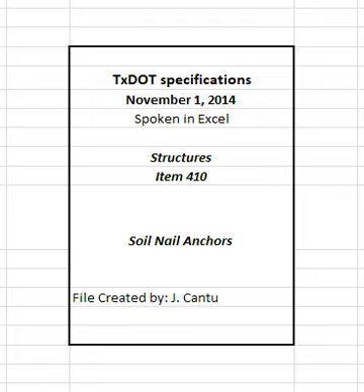Provide a neat cement or sand cement mixture for the grout for soil nail anchors with a 7-day compressive strength of 3000 psi. Determine grout strength by testing the grout used for the test soil nail anchors in cubes in accordance with TxDOT 307D or cylinders in accordance with TxDOT 418A. Test further as directed or if the grout mixture is modified. Fly ash may be included in the grout.